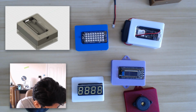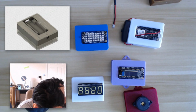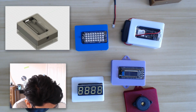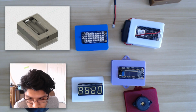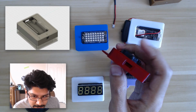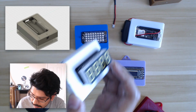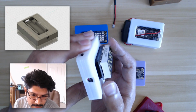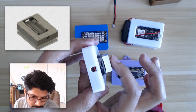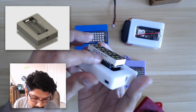Another thing I want to talk about is variable case heights. I'm thinking a slim, medium, and a tall version, like presets where you can have different heights without having to jump into CAD and modify a user parameter. It'd be nice to just have them available. So I'm thinking this version would be slim, the 10 millimeter version, then maybe a 15 millimeter version and a 30 mil version that encapsulates the whole case. Here's an example of one that's way out there. This is double the case, 20 millimeters or more, just because this 7-segment display is so thick.